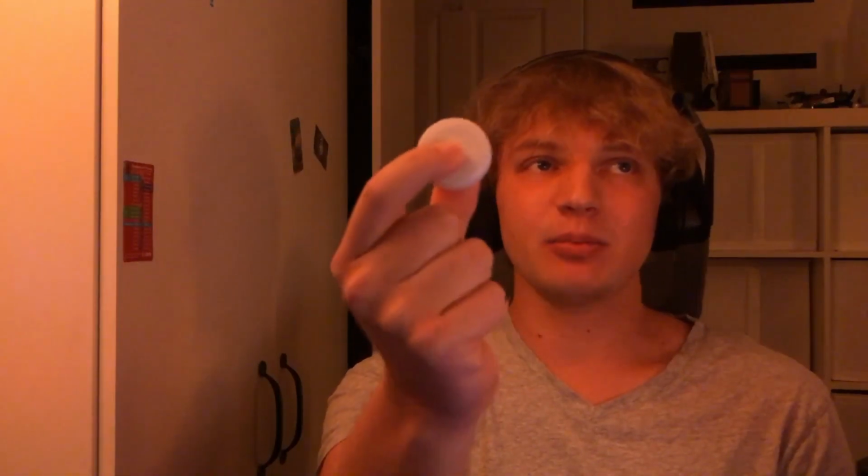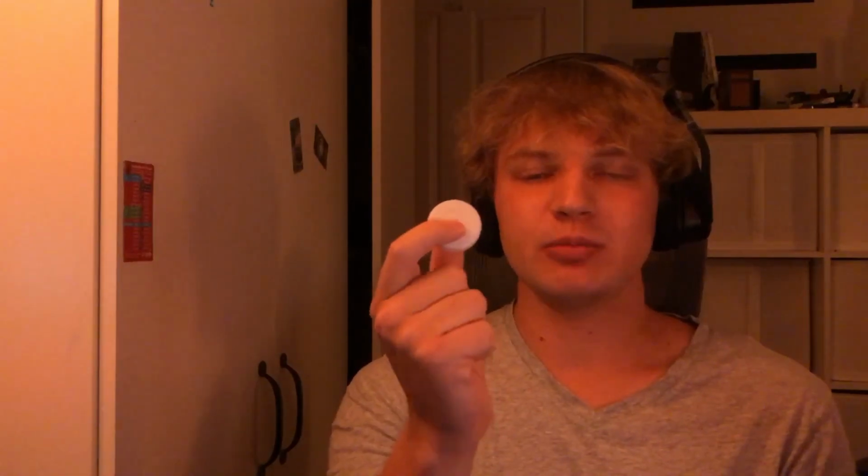So these Bluetooth Low Energy beacons, what they do is they are constantly broadcasting an advertisement packet, just like we saw in nRF Connect. But they are non-connectable. What this means is they are broadcast only. Why would you need a broadcast only beacon? What's the point? Well, think about AirTags. Apple AirTags are actually an example of broadcast only Bluetooth Low Energy beacons.